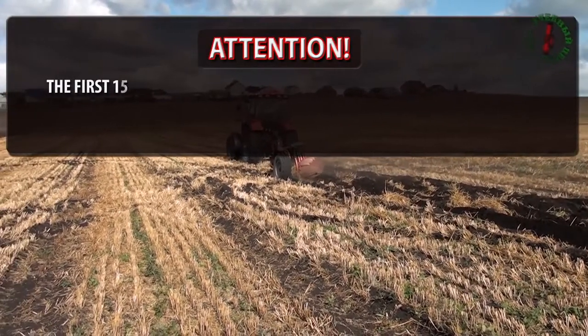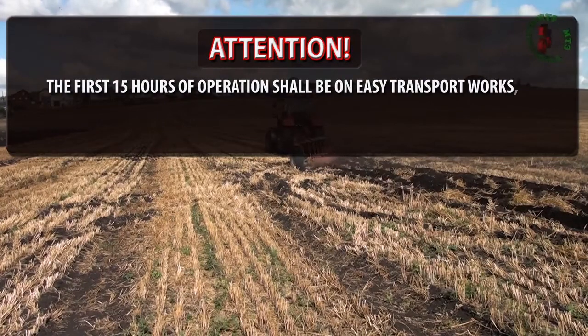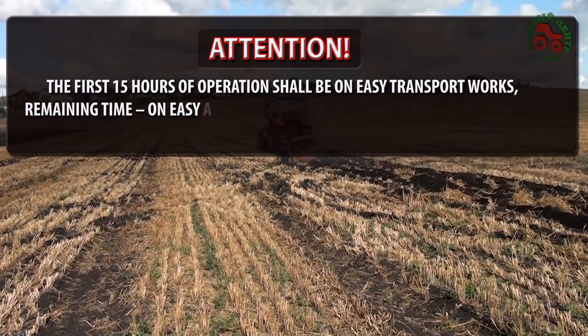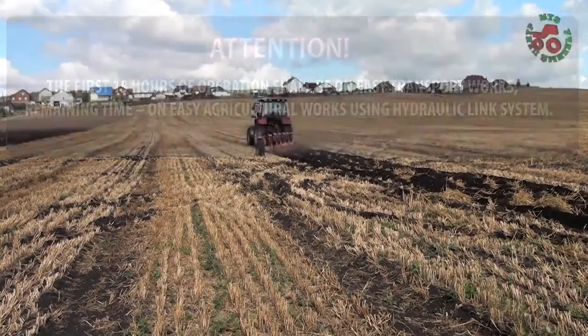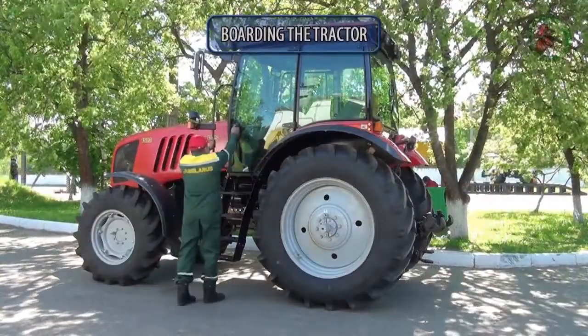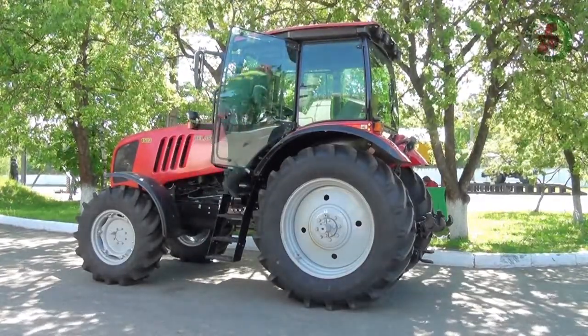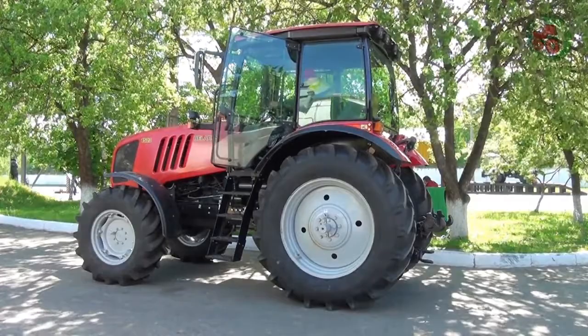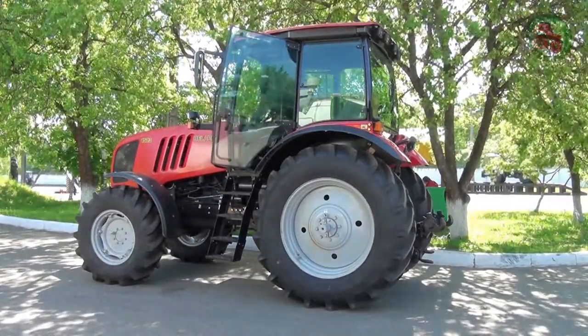The first 15 hours of operation shall be on easy transport works, the remaining time on easy agricultural works, using the hydraulic link system. Boarding the tractor. Boarding, entry in the cab and exit from the cab are done through the left door, holding the handrail, facing the cab.